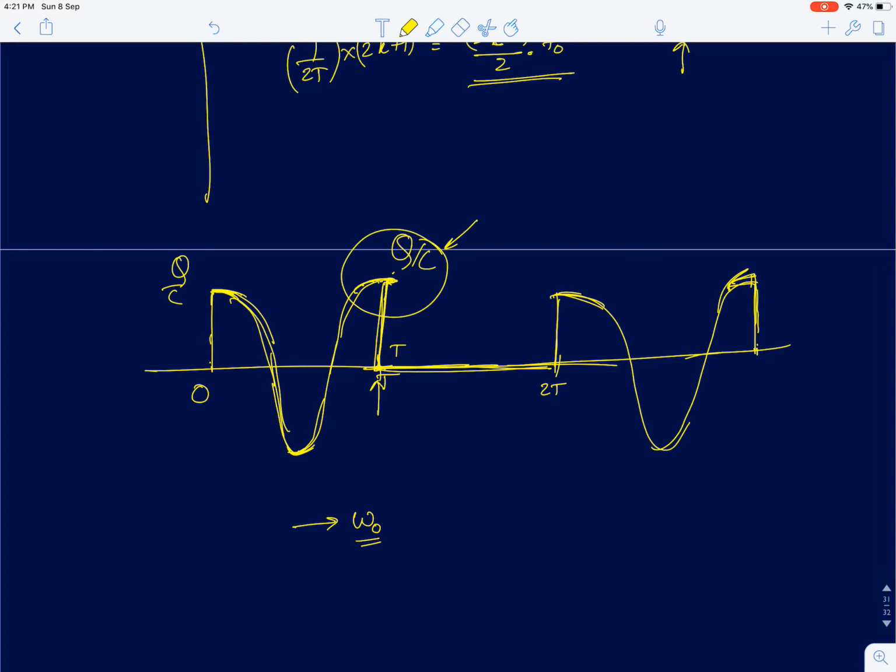So in this lecture I mainly wanted to discuss the sinusoidal response of LC circuits, tank circuits. We saw that when you feed a sinusoid of frequency which matches the resonant frequency, the output was a linearly growing sinusoid. Eventually the amplitude became infinity, and the stored energy in the tank also becomes infinity. And we saw that if I give a frequency which is slightly different from the resonant frequency, then the amplitude and energy stored in the tank will never blow up to infinity.